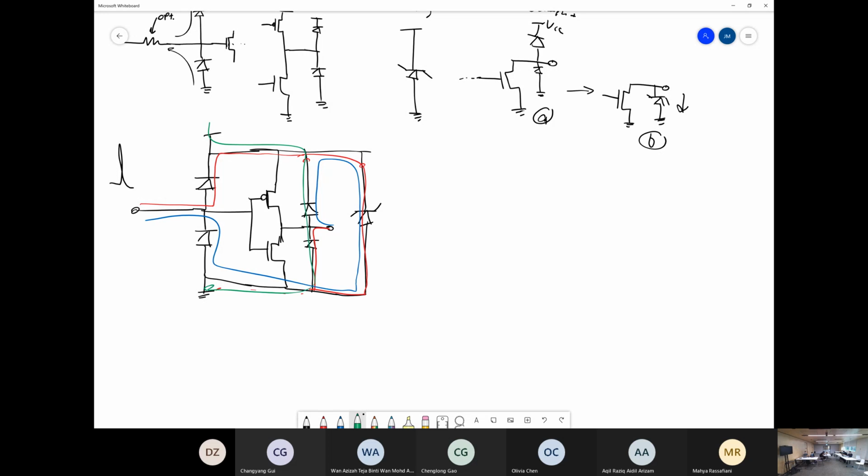Yeah, fairly straightforward then. So the idea is that you trace the direction of the diodes. You just follow the diodes. That's all you have to do. And for a Zener, you can easily reverse break that down. So it's okay to go in the opposite direction of a Zener. Granted, it's constructed correctly, but here we have to assume it is.